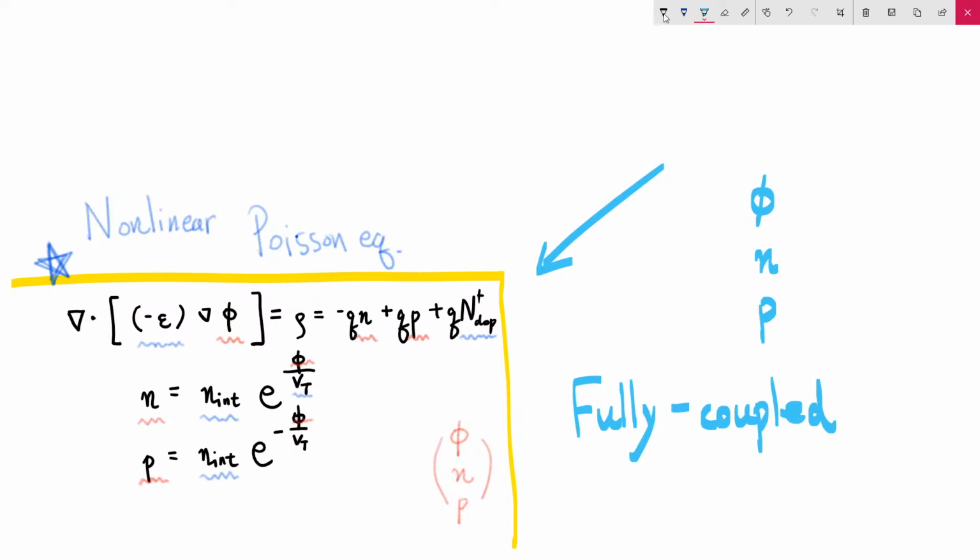So here we have phi and n and p, and please do not, for example, fix some of them as a given number and solve one variable, and after that solve another variable sequentially, expecting that the system will eventually converge. Of course, that is another way to have a converged solution, but I am not talking about such a so-called Gummel type iteration method. I am just asking you for the fully coupled scheme.